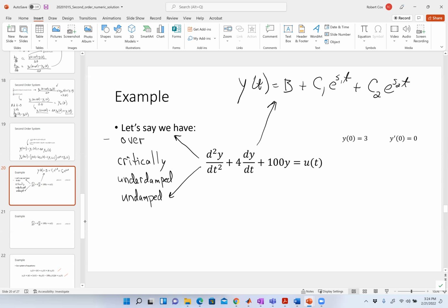What happens when I'm undamped? Completely undamped, in other words, there's no resistance. You had that in the last problem on the last homework. This term was 0, it didn't exist. That was the undamped case. You just have a sinusoidal function. This one's a pure sinusoid. This one just dies. What does underdamped do? Well, it's a sinusoid that goes away.